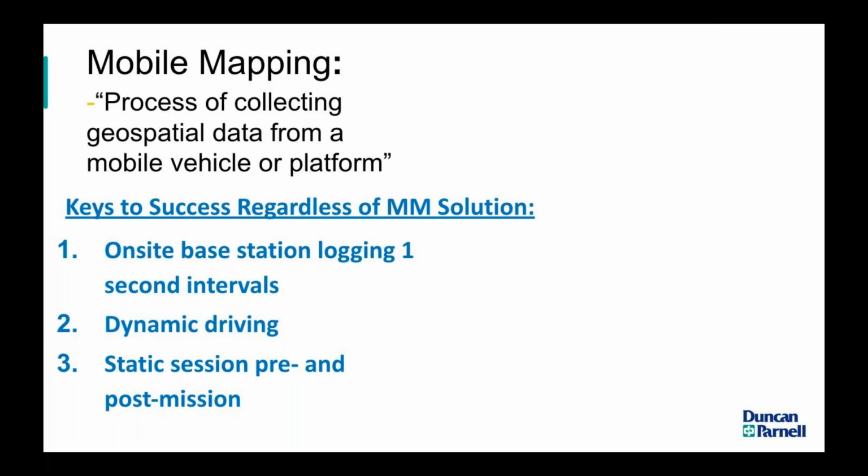Now, of course, if you're just doing some GIS asset extraction, sub-meter, several feet is sufficient. You may be fine without a base station, but if you're doing the higher-end engineering survey level accuracy projects, that really is critical. And those latter two are all about best practices in the field as far as how your operator is driving their system.